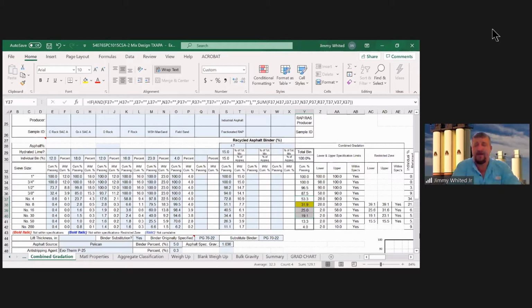So we have in-house Excel sheets, and we just put them on the Google Drive so that any technician can now log in. We run daily moistures, and we run weekly stockpile samples for gradation, and all of this is logged. You can go in and look at a 7, 10 day, or do a 6-month average to see what your moistures are coming in at.